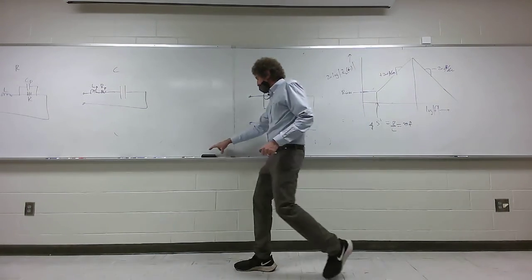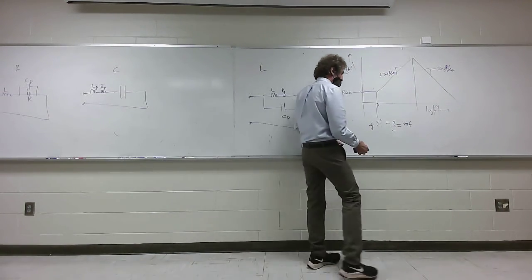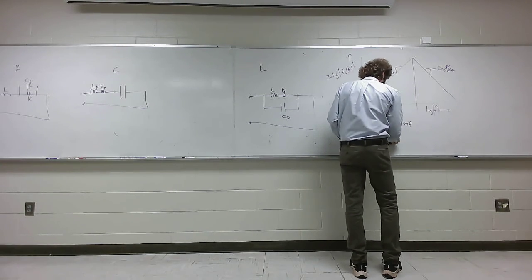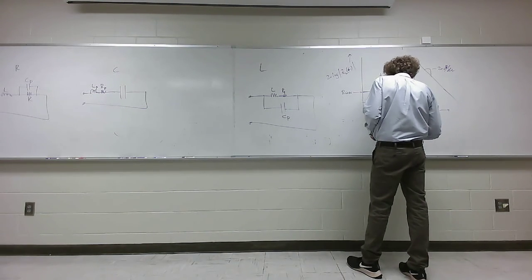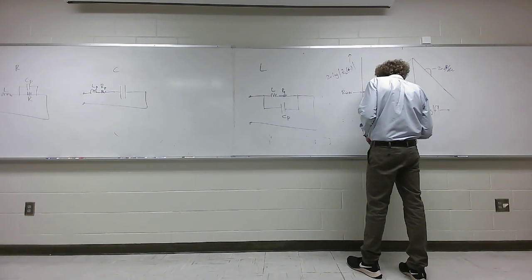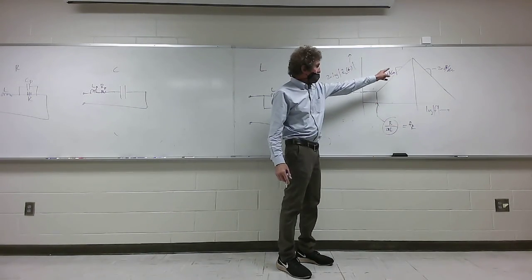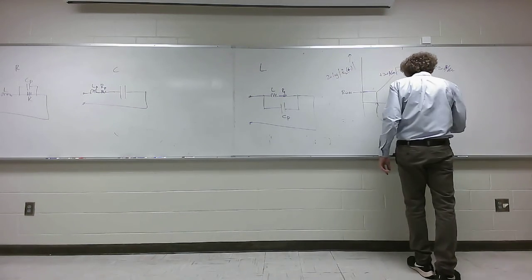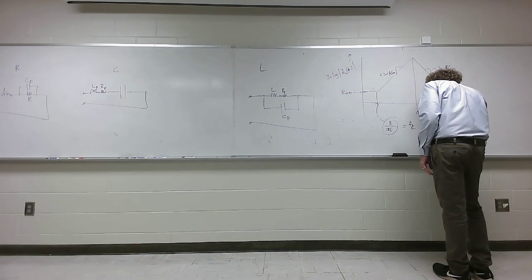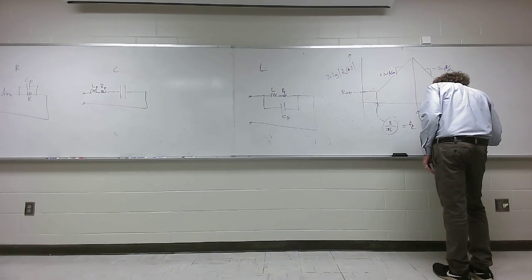The low frequency pole is simply R over 2 pi L, this would be F low right here. This, most of the time, you don't even worry about. You just worry about this point, and this is at self-resonance. And this F self-resonance here is equal to 1 over 2 pi square root of L C parasitic.